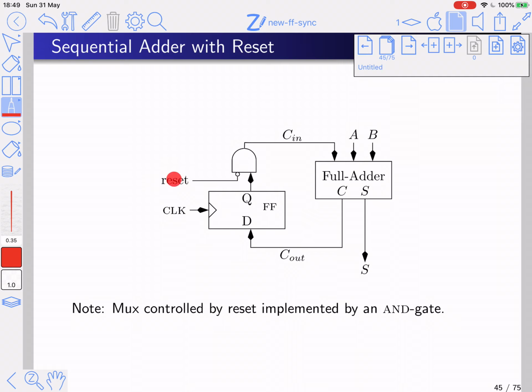If the reset is 1, then the output of the AND gate is 0, because there is a small inverter before the AND gate. And if the reset is 0, then you feed a 1 into the AND, and therefore the AND simply outputs what is input through this port. Okay? So this is a way of resetting Cn to be 0 in clock cycle 0.